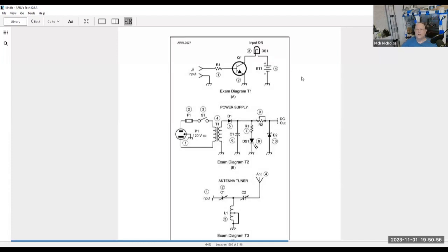Doesn't matter which way you think of it, but the truth is the base controls. This is an NPN right here because the arrow is pointing out, that's negative. If the arrow was pointing in, it would be a PNP transistor. Then this side would be wired to plus on the battery, and the other side of the bulb would be wired to ground. It would work the same, except things flow the opposite way.